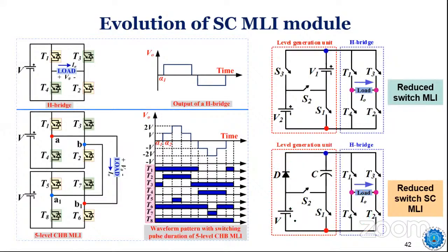So as I have got twice voltage boosting, you may think whether, if I connect this type of inverter in a photovoltaic system, I need a boost converter. See, when I connect a boost converter, that is to boost the voltage to 2 times, generally by maintaining the duty cycle. Let's suppose I maintain around 0.5, I can boost the voltage to 2 times. Here, without any boost converter, from the input voltage V, I am getting 100 volt. That is with the help of this capacitor voltage. So I am boosting to 2 times without any boost converter. So we do not need an additional boost converter.